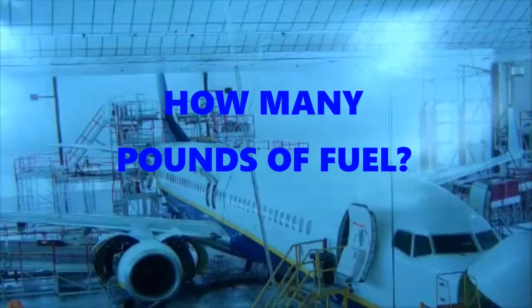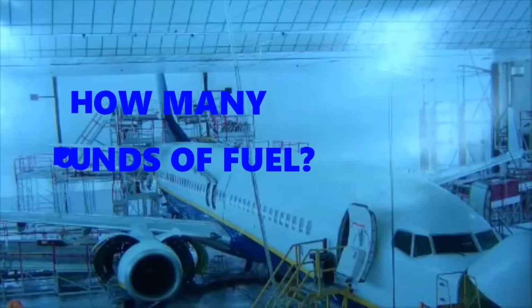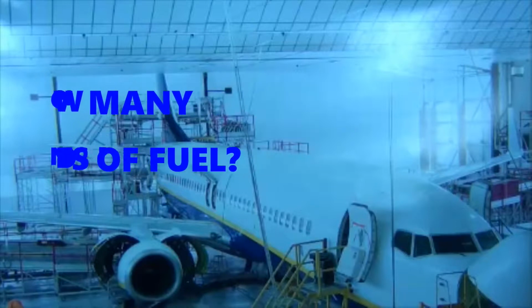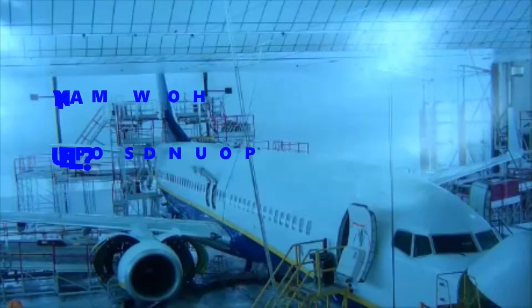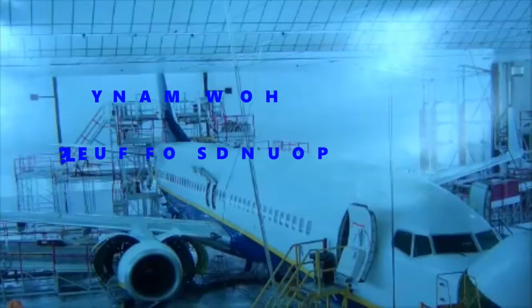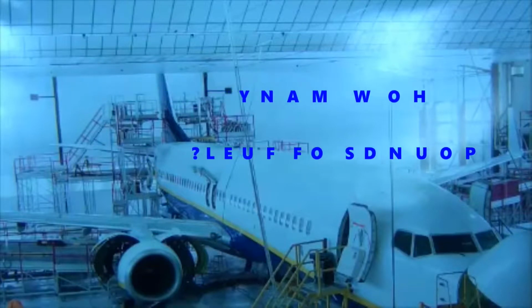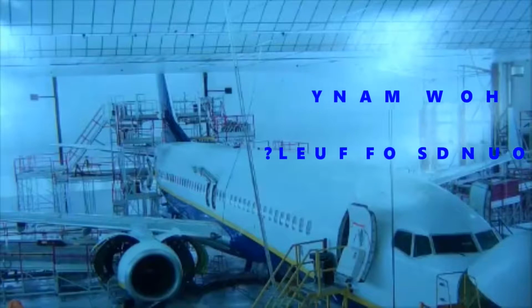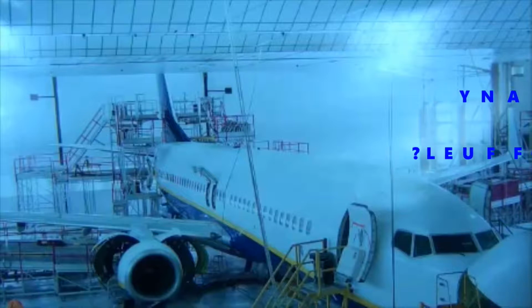Okay. So remember I mentioned a bit ago about the outer cell and the inner cell. The inner cell holds a lot more than the outer cell. So the outer cell is going to be filled first, okay? Then it's going to spill over into the inner cell. All right, so that's with your fuel tanks and the nature of the wing tanks, the way they're structured, as you have an outer and an inner cell.